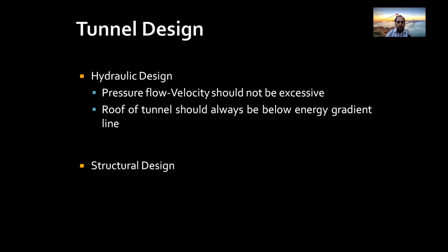Otherwise, what will happen? Scouring will take place. Generally, in case of concrete-lined tunnels, we provide a maximum of 5 meters per second. And in case of steel lining, we can go higher, but generally we don't go for more than 7 meters per second. And the roof of the tunnel should always be below the energy gradient, because if the hydraulic gradient line